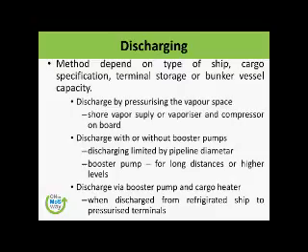So the discharging method depends on the type of ship, cargo specification, terminal storage, and bunker vessel capacity. What we are technically doing is discharging by pressurizing the vapor space. But mind that we can only pressurize a type C tank, which can sustain certain pressure. We cannot pressurize membrane tanks, because otherwise we will damage the tank.